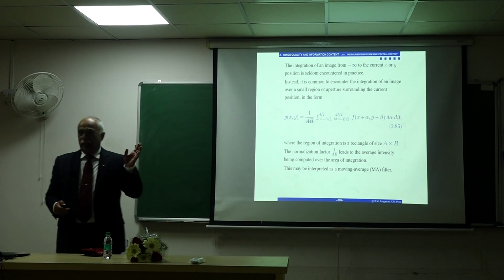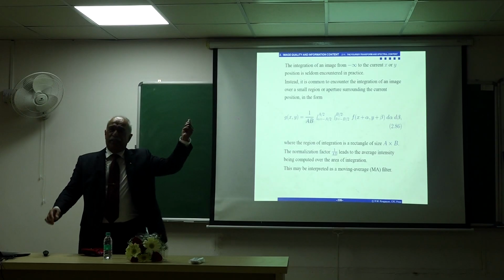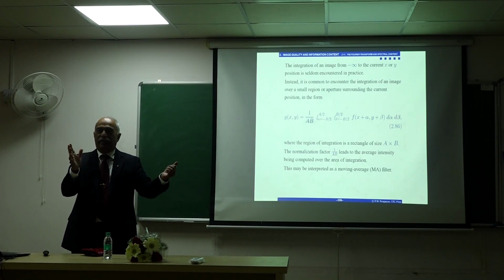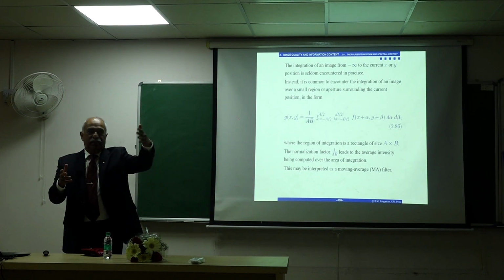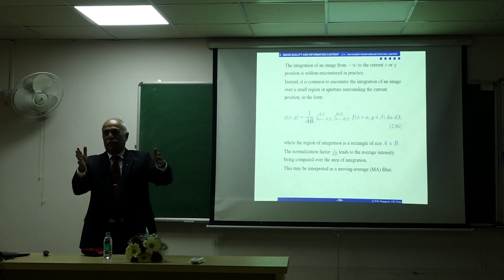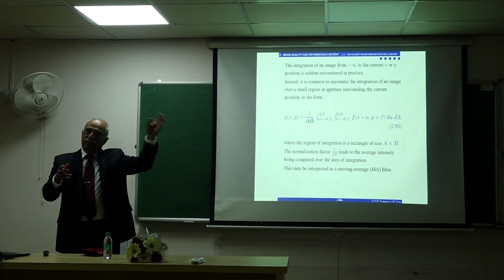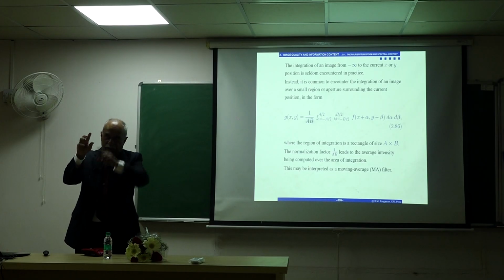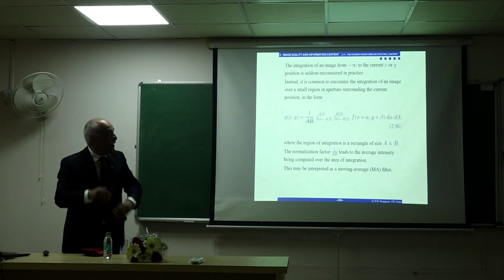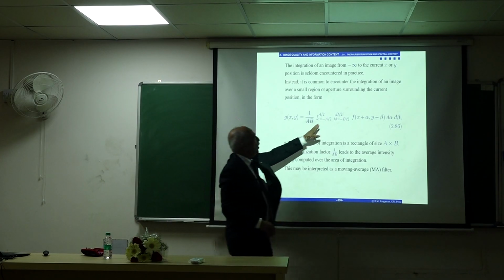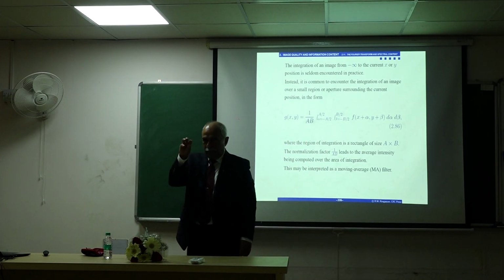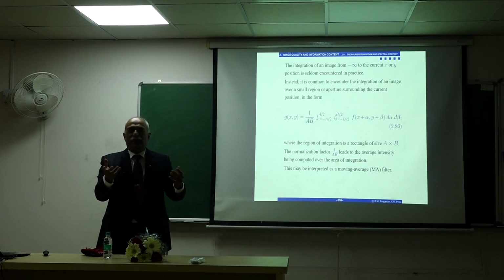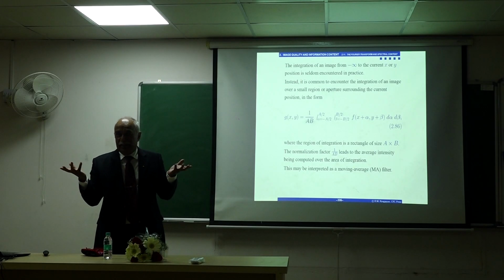Now in signal processing, sometimes you may integrate from minus infinity to the current time, usually in theoretical representations. But in practice, there is an origin somewhere and you integrate from there. In image processing, you don't start from somewhere in the image, you integrate over a small area, not from the origin, wherever that is. So you integrate over a small window or aperture. There is no need to integrate over the whole image. If you integrate over the whole image, you get the average value, that's useless.